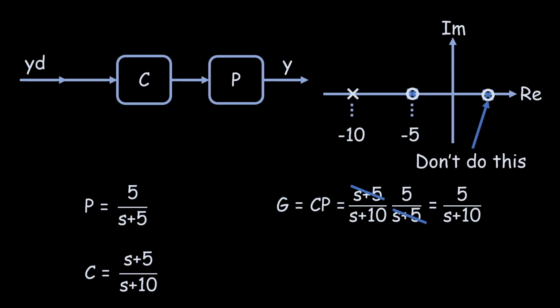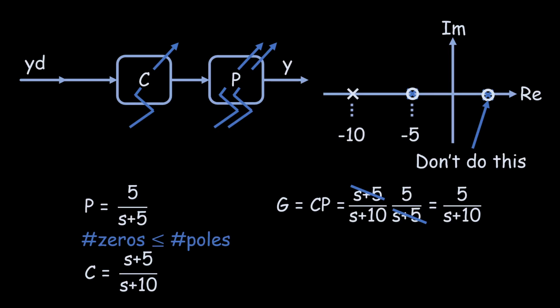For example, the system will change over time. The parameters obtained from system identification are not perfect, and there is numerical error in the processor's calculations. Additionally, the number of zeros in the controller cannot exceed the number of poles. Otherwise, implementation will be impossible.